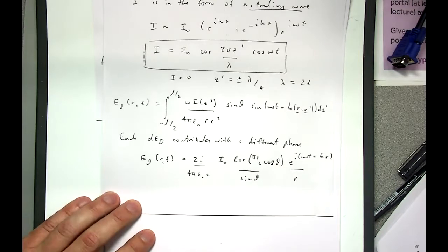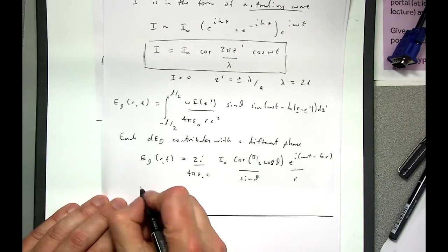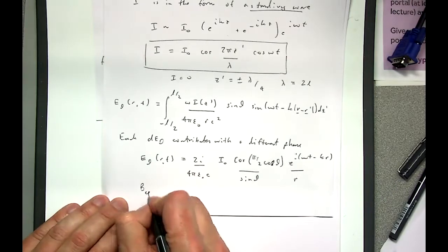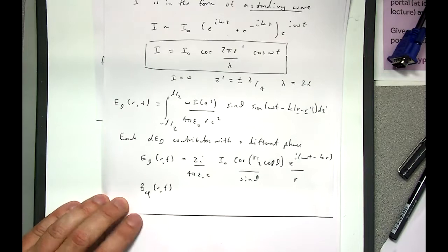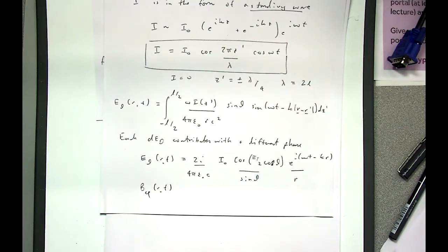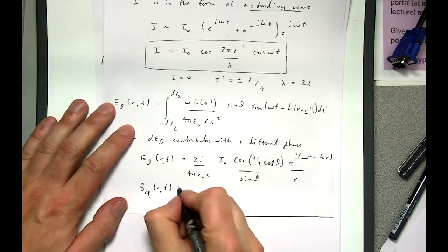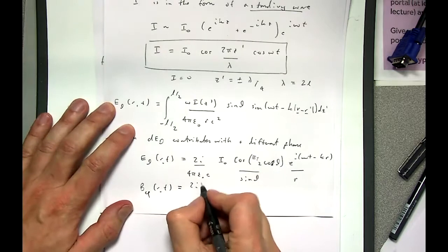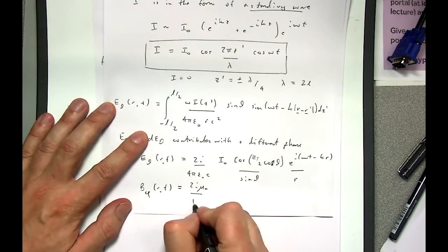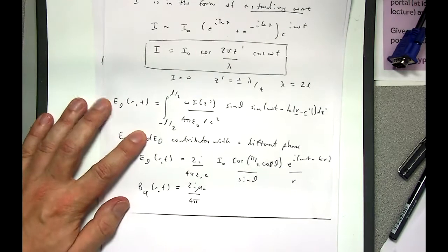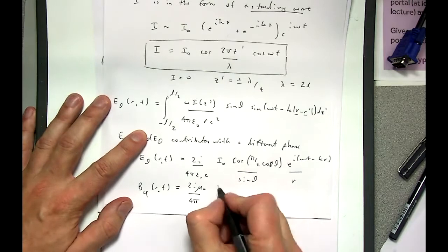And because it's far field radiation, whatever's happening with the electric field in theta, there must be a magnetic field going in phi, going around. The current goes up, the field goes that way. And that looks just the same, except it's got some mu naughts that appear instead of epsilon naughts, to make sure the magnitudes are right, but everything else is the same.